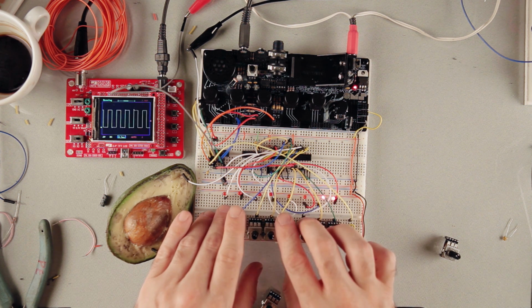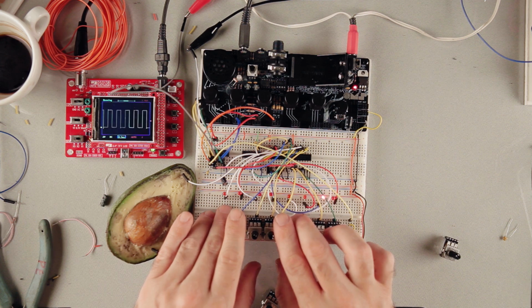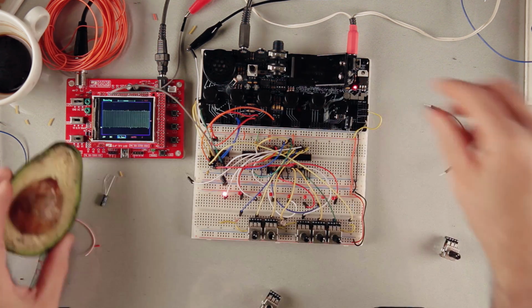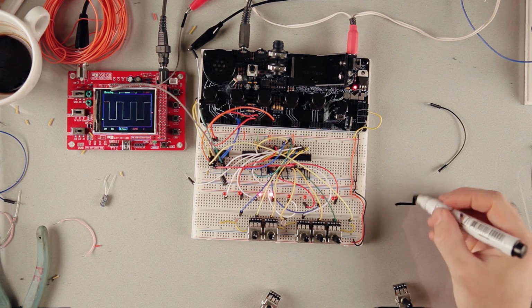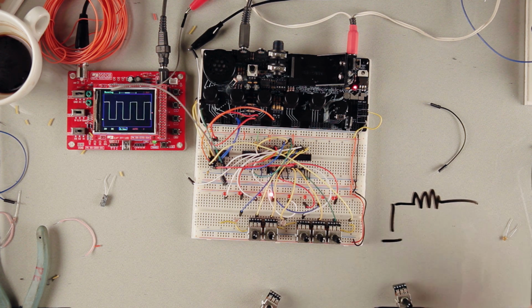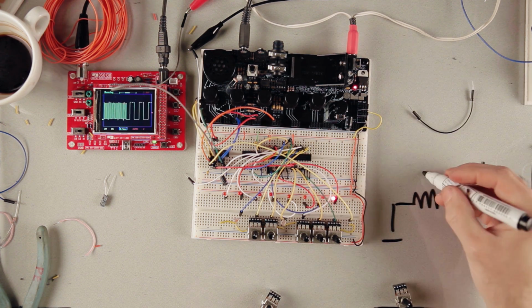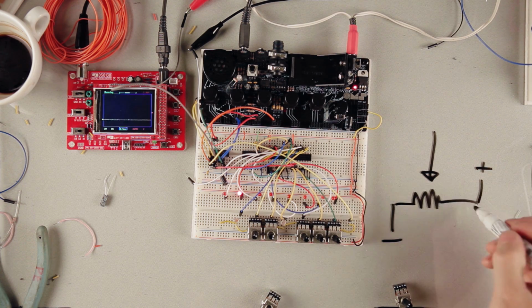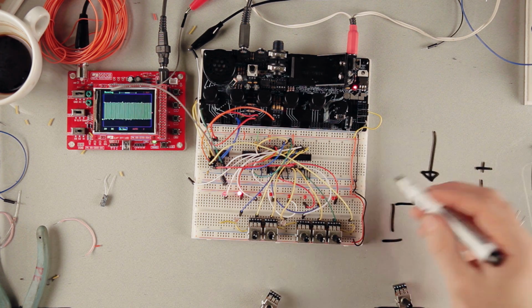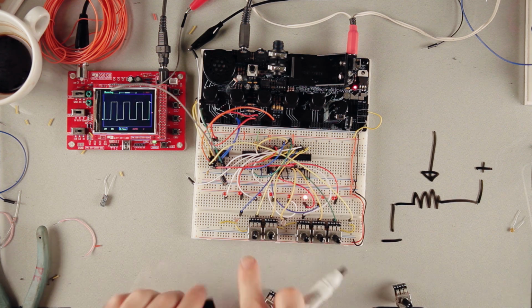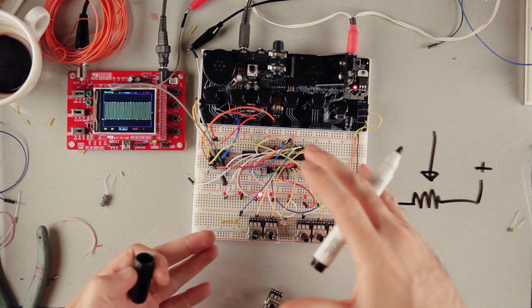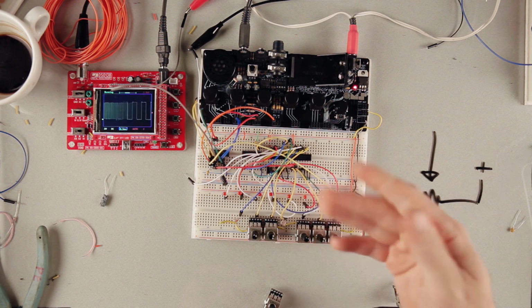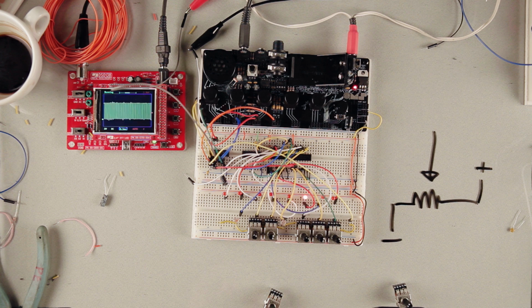There, it's the potentiometers. But I could also turn these into voltage dividers. I would do that by taking all of these potentiometers, and I would run one side to the negative, one side to the positive, and then the output is a voltage. And as I turn the potentiometer to the left and right, it will move between the low voltage and the high voltage. So each of these can be an individual voltage that I send out of this multiplexer. So this can be a sequencer that you can use to control your analog synth, whatever.